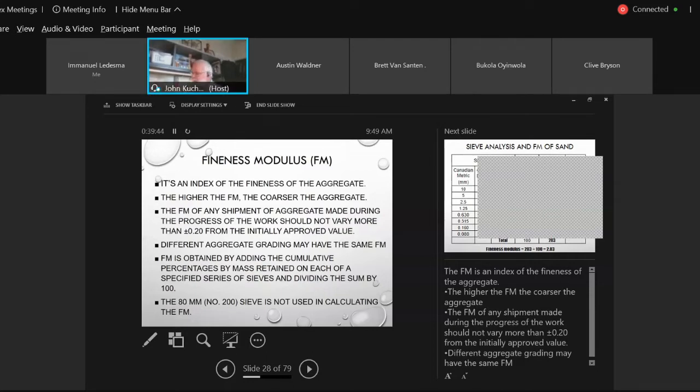So again, and it's very important in asphalt, you have to try and maintain those gradations as close to the gradation that you use for designing the concrete mix design. Concrete mix design is going to be based on a certain grading. The mix gets approved, you start batching, but your aggregates are all changing, well, now your mix design is not going to perform because the aggregates are not the same. You'll never get them exactly the same, but you're going to have a plus or minus tolerance, and the city of Winnipeg shows that.